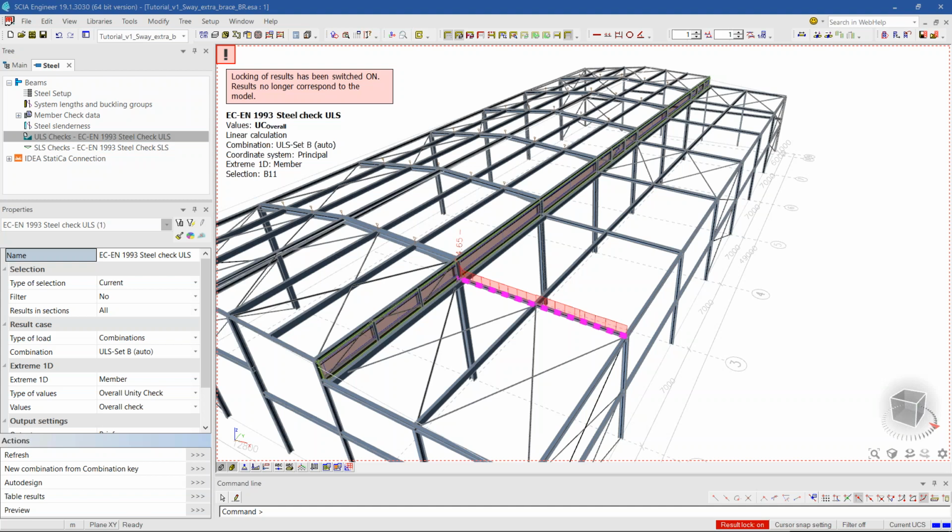Why 75 modes and not 100? It is simply because I try to achieve factors bigger than 10. If your structure requires it, or if it needs fewer modes, you can probably pass with less. As long as you pass the mark of 10, I think it is fine.